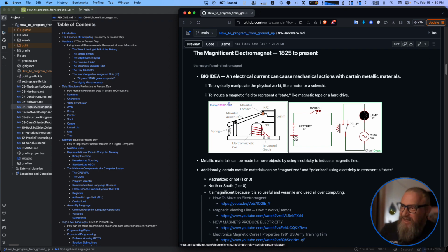So one side goes up to this battery, and the other side goes to this side of the switch. Right, and when the switch is thrown, that magnetizes this thing that pulls the armature, which is held open by a spring. Normally, this is a normally closed one. And so when the magnet here is magnetized, it pulls that handle over this arm, boop, and then makes that circuit go right here. This thing goes boop, and the circuit goes.